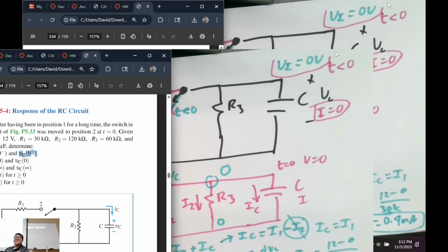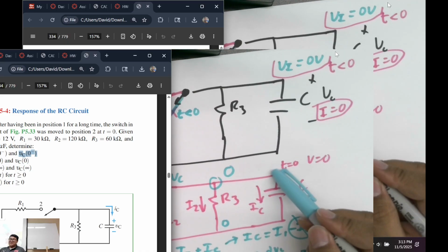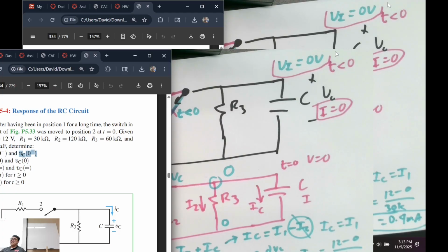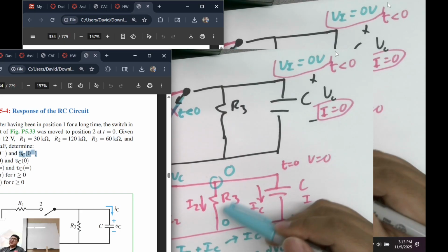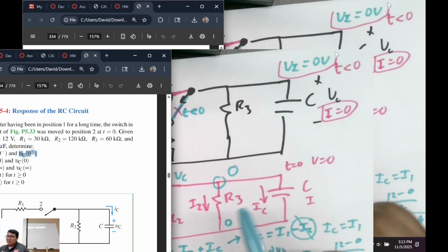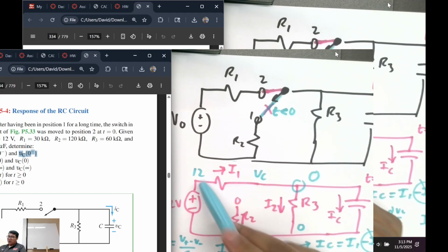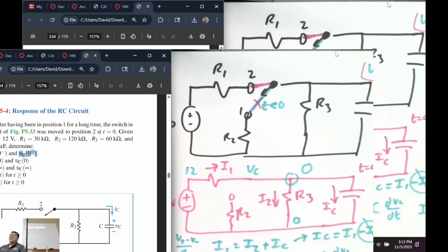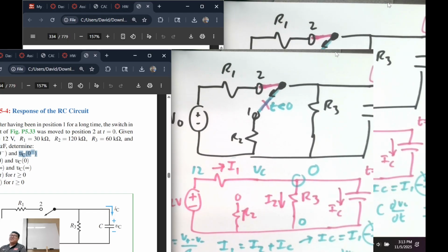It feels good, right? Why was this I2 gone? Because the voltage here was 0, right? Let's not forget our fundamentals, okay? Even I forgot a little bit. I'm like, wait a second. There's 0 here or 0 here. That means no current, correct? But there is a current because the current right here is generated, 12 to 0, divided by that resistor. All the current is being sucked into that initially, okay?